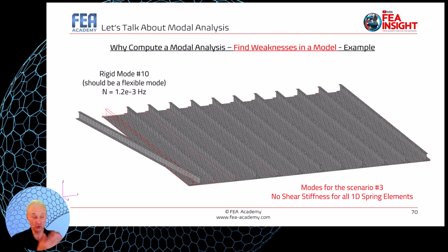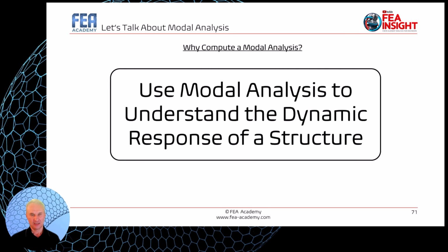Don't look only at the table of frequencies. Plot and animate the mode shapes associated with each natural frequency. The last usage of modal analysis I want to show you here is to use modal analysis to understand the dynamic response of a structure.